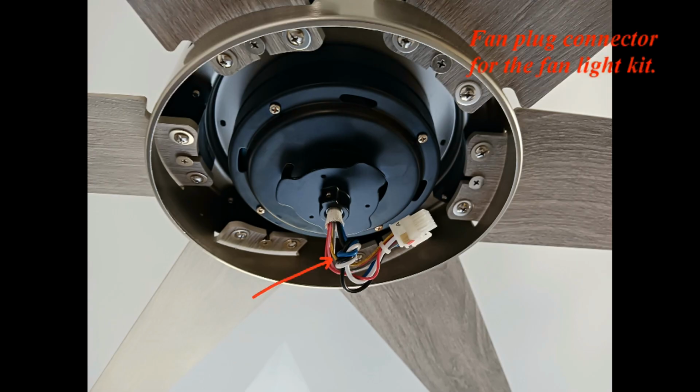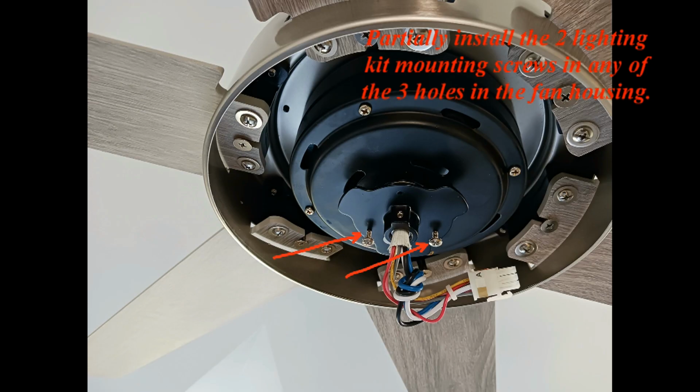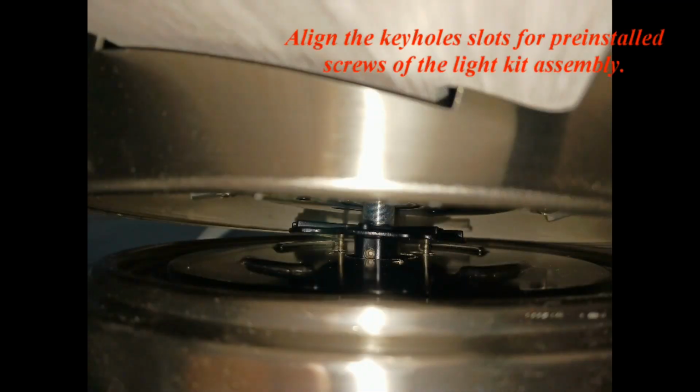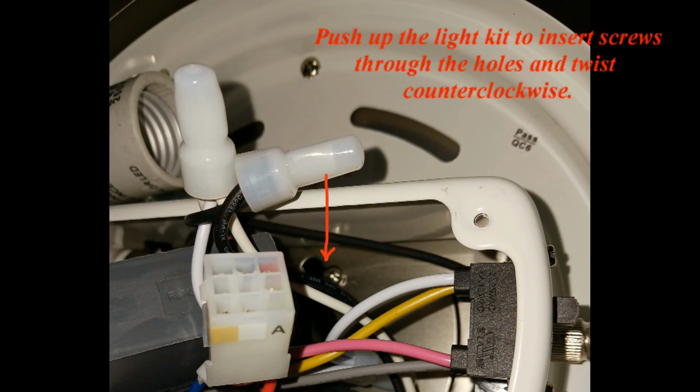Fan plug connector for the fan light kit. Fan housing screw holes for fan light kit installation. Partially install the 2 lighting kit mounting screws in any of the 3 holes in the fan housing. Feed the fan plug connector through the center hole in the light kit assembly. Align the keyhole slots for pre-installed screws of the light kit assembly. Push up the light kit to insert screws through the holes and twist counterclockwise.